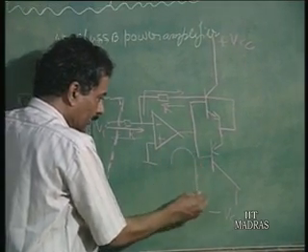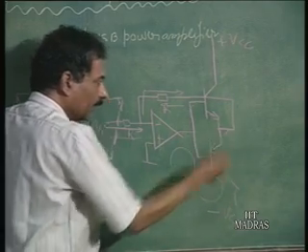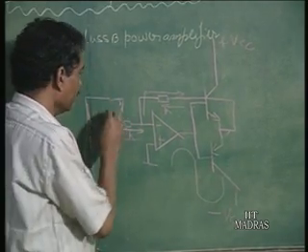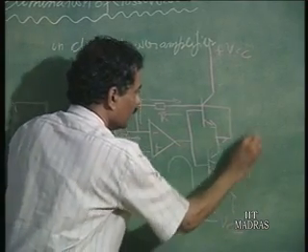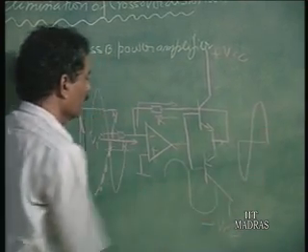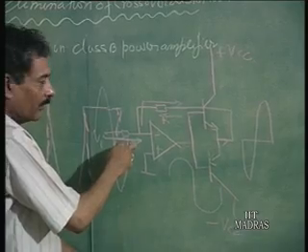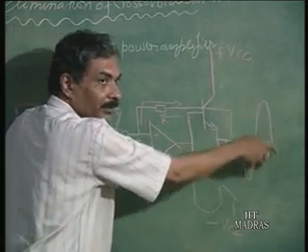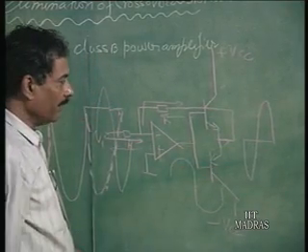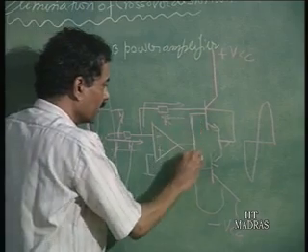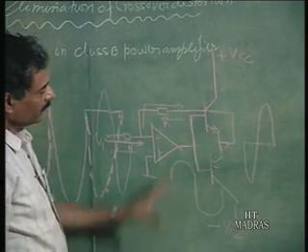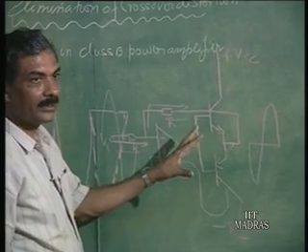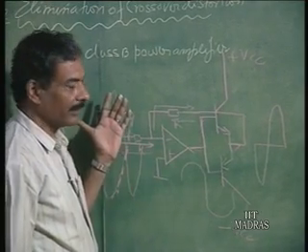And here it will be absolutely a sine wave, even if the sine wave amplitude is going to be very small. This is going to be inverted here and going to appear here as a perfect sine wave in spite of the diodes conducting only after cut-in voltage is applied. So this is clearly demonstrated in the case of the precision rectifier as well.